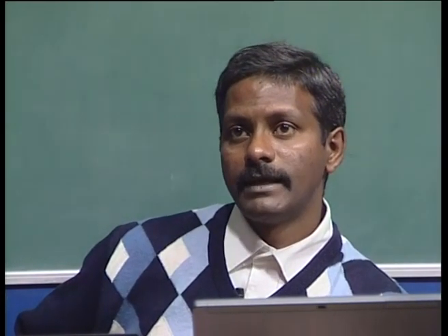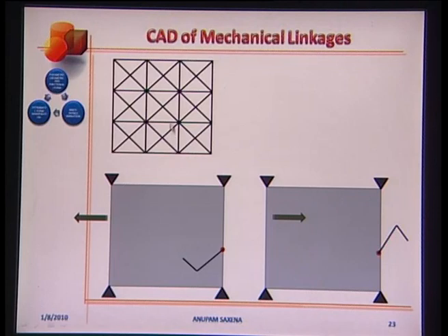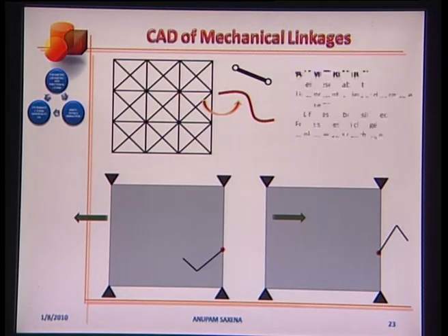First, we parameterize the design through a network of lines. Each line can be present in or absent from the layout. If present, the line can either have the characteristics of a rigid member, shown in black, or a curved, deformable member, shown in red. Further, nodes, that is, all the intersection points between the lines, can be repositioned. The shape and in-plane widths of a deformable member can change.